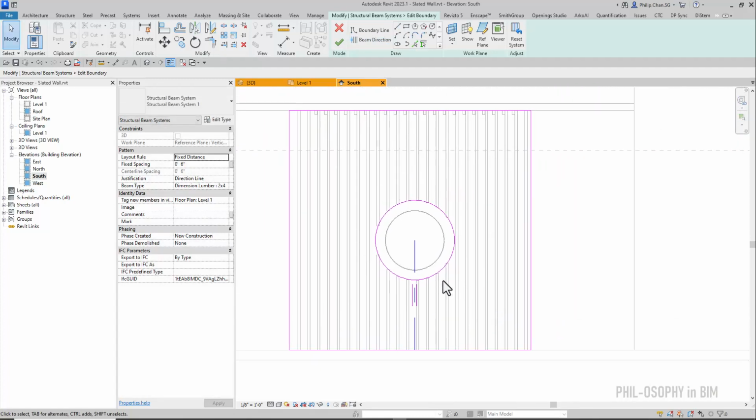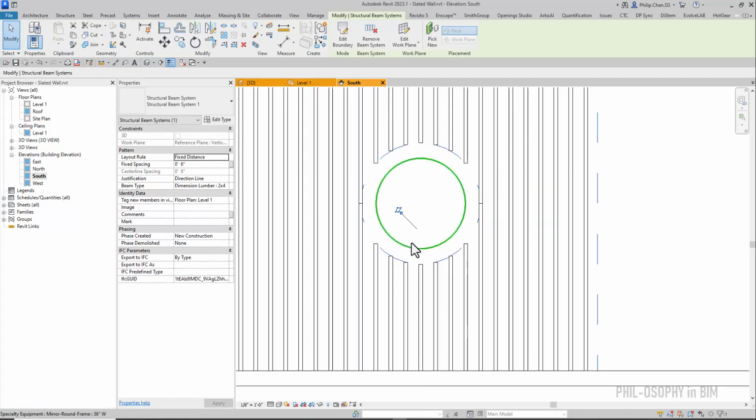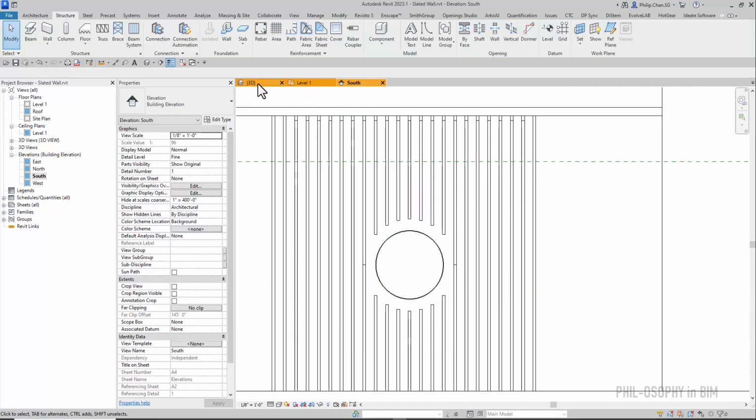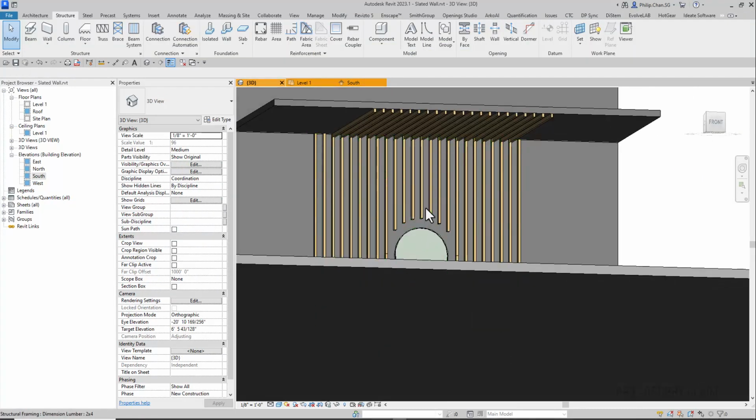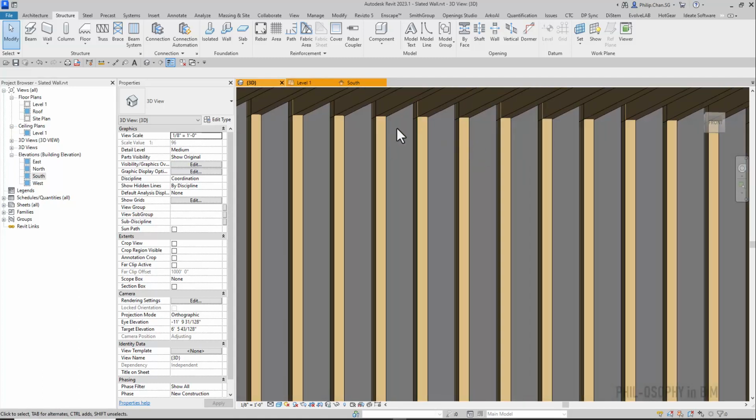What that means is now I'm telling Revit that my beam is going to go from this line, and they're going to be 6 inches apart from the left to the right. Alright, let's go and finish it. And you can see that my beam now, my first one, is adjusted to the center of my mirror. That's how you do it. And now you'll see that my ceiling and my vertical one all happen to align.